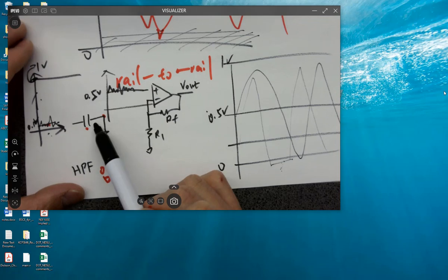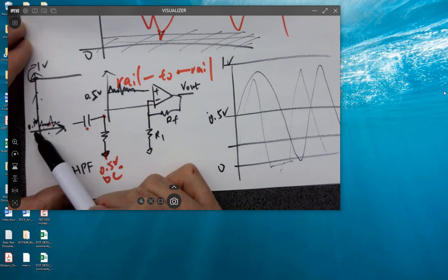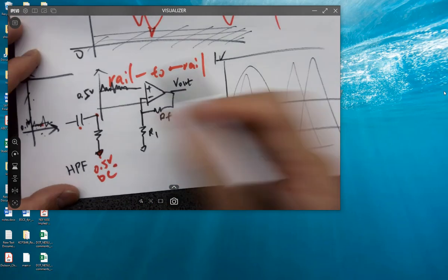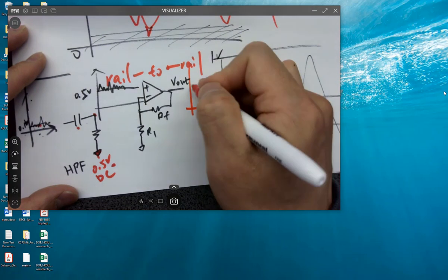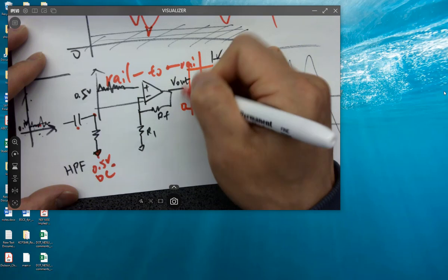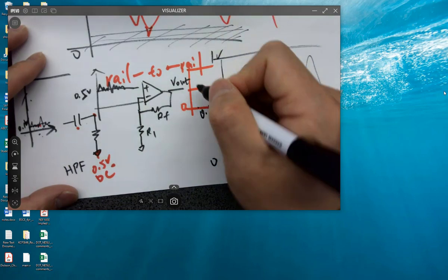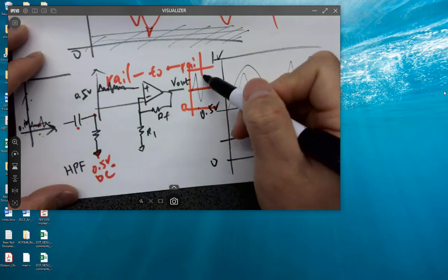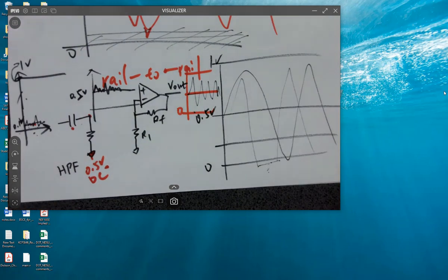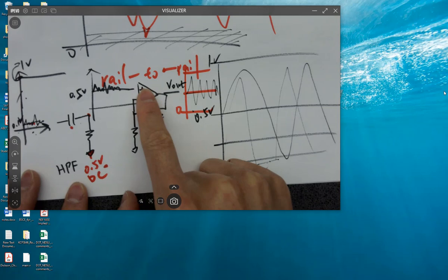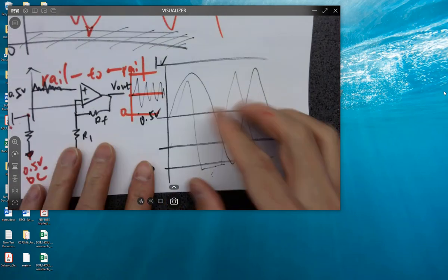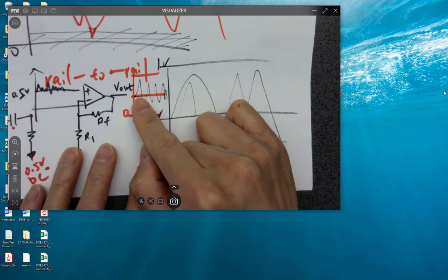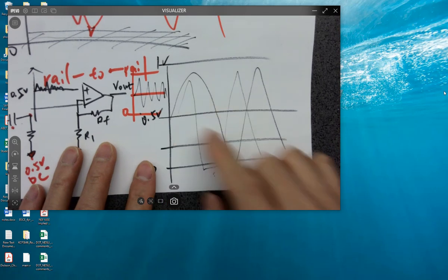So this removes the random DC offset first, and then amplify it, and then lift it, and then amplify it. So after the amplification, you are getting this 0 to 1 volt range. The voltage becomes bigger, but still swinging around that ideal DC offset in the middle. So it's gonna do this, right? You may need more than one stage. In that case, eventually you have this AC signal swinging around that ideal or better DC offset, which is in the middle, and eventually you can digitize it.